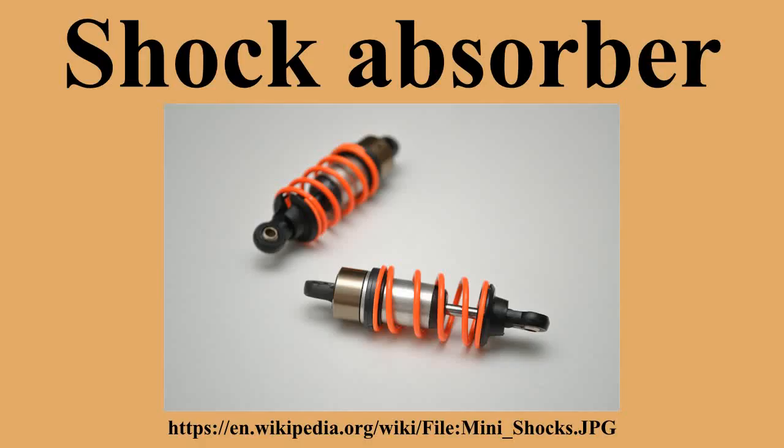Most vehicular shock absorbers are either twin-tube or monotube types with some variations on these themes. Twin-tube: basic twin-tube, also known as a two-tube shock absorber. This device consists of two nested cylindrical tubes, an inner tube that is called the working tube or the pressure tube, and an outer tube called the reserve tube.